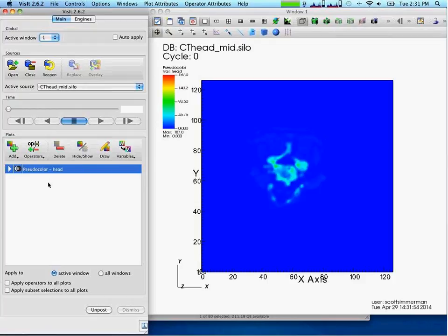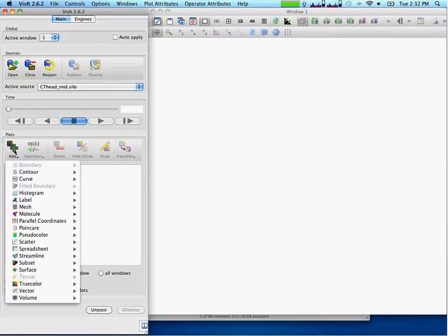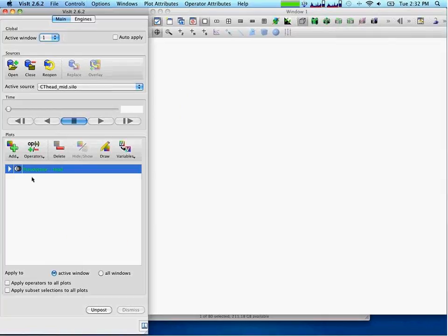That was probably too quick to see, so notice there's a color change when we first pick this, over here in the list, which means it's ready to be rendered. It doesn't render automatically, and again, it goes back to the thing that it doesn't seem very responsive. You'll make a change and you won't see anything unless you click apply or click draw. The reason it does that is it's designed to deal with very large data. So a lot of times, one change you make will, underneath the hood, be a lot of computing, a lot of things have to happen.